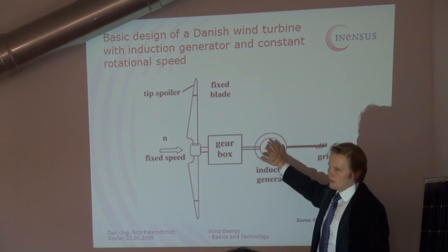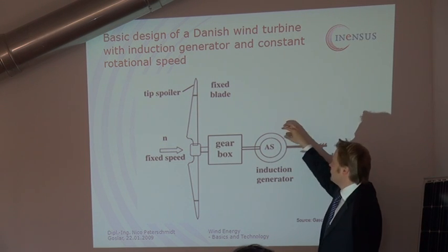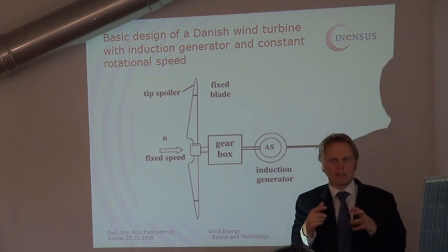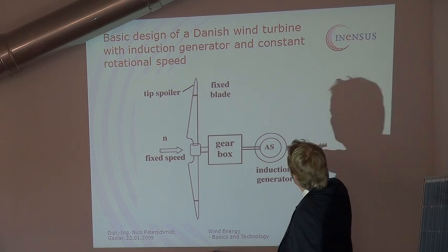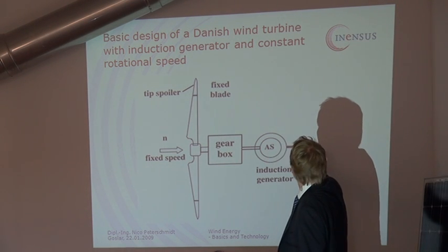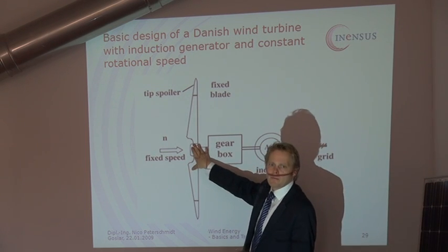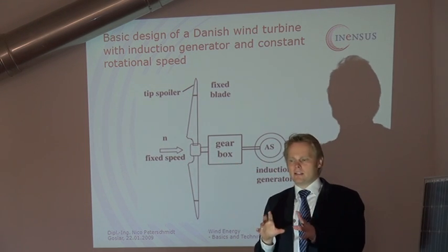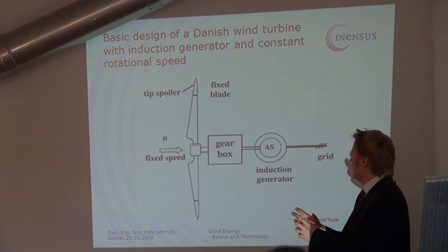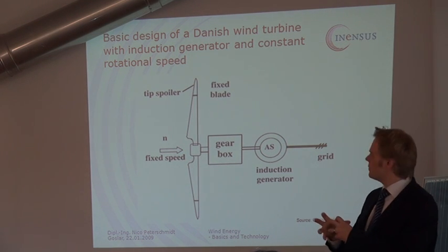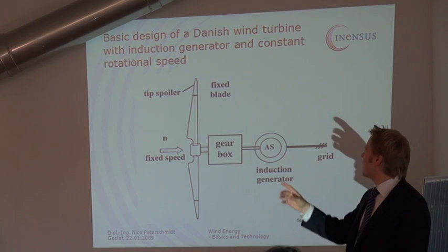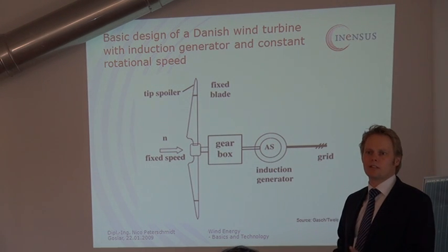The rotor is rotating. And then if you put a frequency on the rotor, you can make the induction generator, which is coupled to the grid directly with the stator, into a variable rotational speed wind turbine. You simply add some frequency on there, which, related to the grid frequency, reduces the resulting frequency for the rotor.